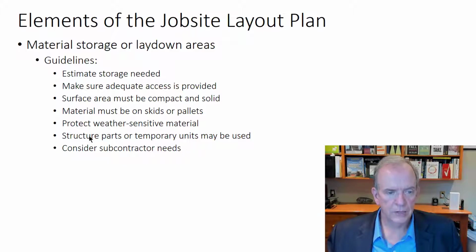And this last one here is a big one too. Consider the subcontractor needs. And be careful with that. Some subcontractors want to bring everything to your site because they got a deal on it or something, and then it's blocking up your site, and it's like a nightmare. So you've got to be really coordinating well with your subcontractors.